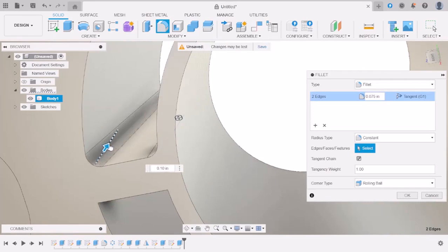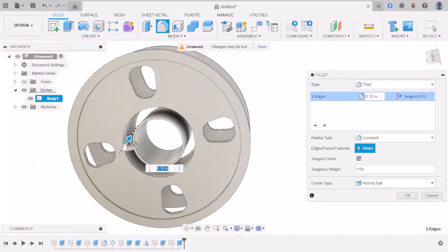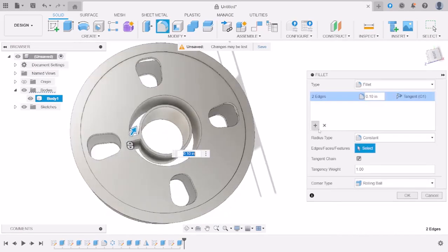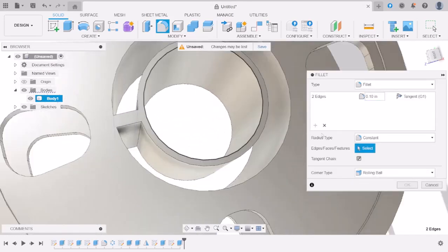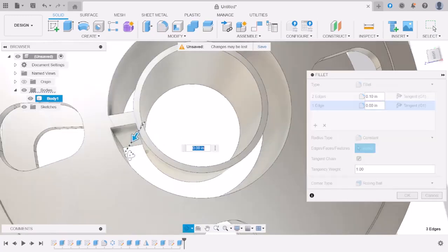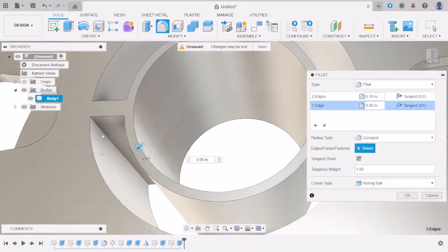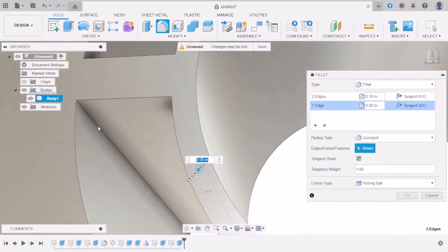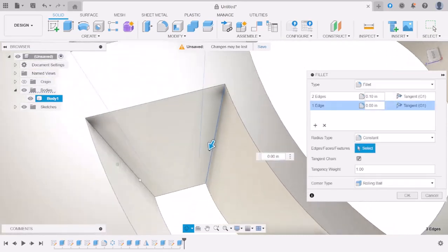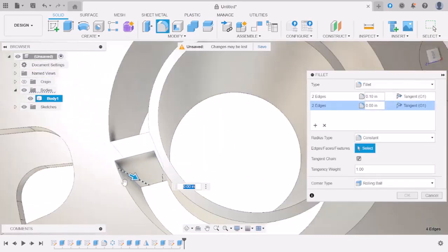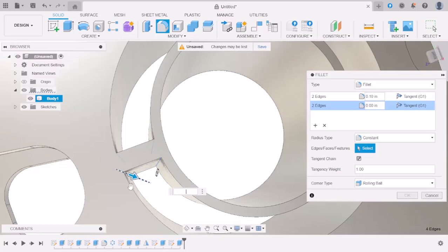And I can come down to this fillet in here and click add a new selection set. This here, add selection set, and I want to extrude this set here to, you can see if I zoom in close without holding this, I can select this one here. Let's see, nice. And we want to make that also a 0.1, and we can say okay.